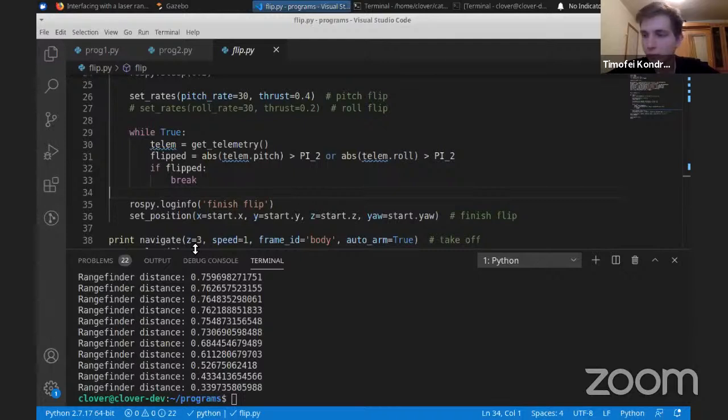If you use the 3S battery, with 3 cells battery, and the PID settings from the settings article on our knowledge base. So if you basically just assemble the drone and set the drone the way that is supposed to be, and use 3S battery, then the flip will work fine on a real drone. Otherwise, it might crash.